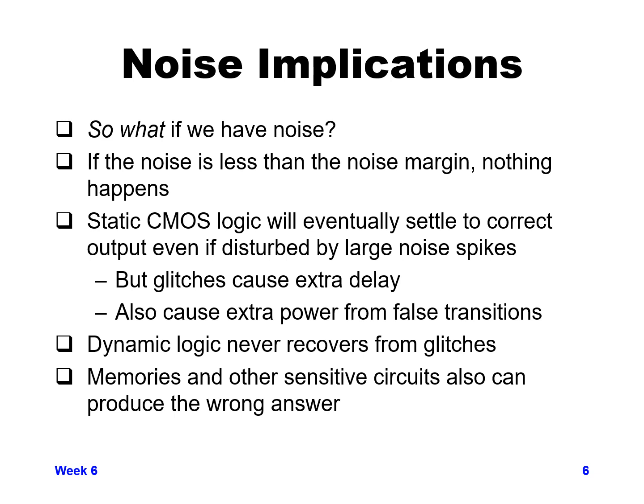More problematic, or more likely to be problematic, is if you're using dynamic logic. Dynamic logic, if it gets a glitch on it, it never recovers from the glitch because it's kind of a one-shot thing. As soon as it switches, it stays in that new state until you get a pre-charge value to come in and reset the dynamic logic. So with dynamic logic, you have to be very, very careful with noise. It's very sensitive, and so that's one of the things that makes dynamic logic quite hard to do.